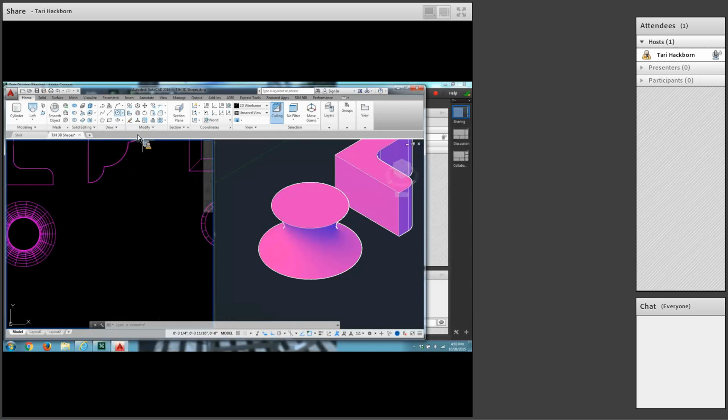They want to show you what's going to happen if you pick the bottom circle, the top circle, and then the middle circle. First circle has a radius of 3/4. Oh, that's a little bigger, isn't it? Okay, maybe I should move that a smidge. Ortho's on, so I got to move it twice. Once down and once over.